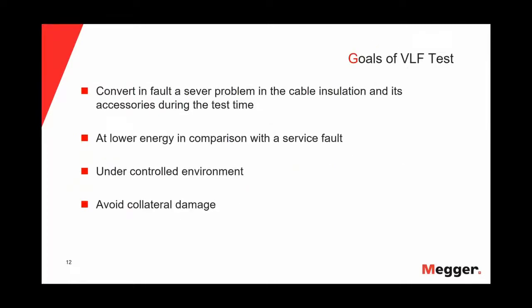The goals of the VLF test are to convert into a fault a severe problem in the cable insulation and its accessories during the test time, and at lower energy in comparison with the service fault. So this is very important, and we will do this under a controlled environment, and we will avoid, of course, collateral damage.